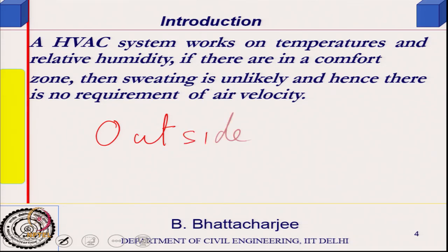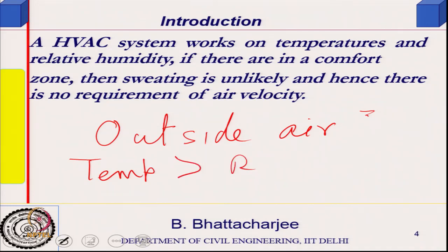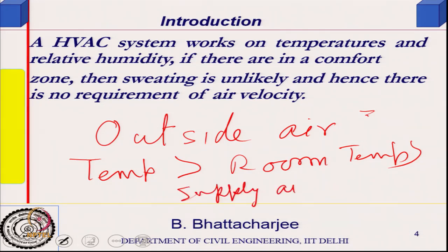So, outside air temperature is greater than the room temperature, and this will be further greater than the supply air temperature. So, what I have to do is cool the outside air to this temperature.